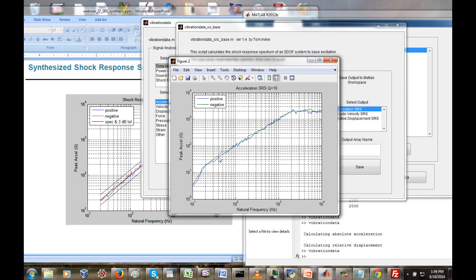But as long as the natural frequency of our component is, I'm using 40 hertz because that's 1 octave above 20 hertz. So as long as we have 40 hertz or higher, we're probably not worried about that response energy down there. But on the other hand, sometimes we might have an isolated component, and our component might be isolated to 20 to 30 hertz. And in that case, we'd have to be a little more careful, and we probably should extrapolate our spec down to 10 hertz, which would be, for this case, 10 hertz, 10 Gs. So that would have been a little bit better choice, but again, it just kind of depends on what the natural frequency is.